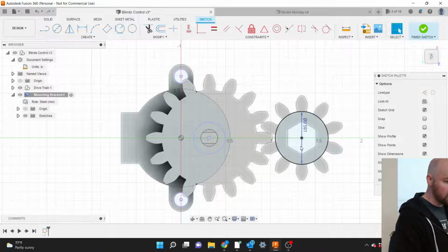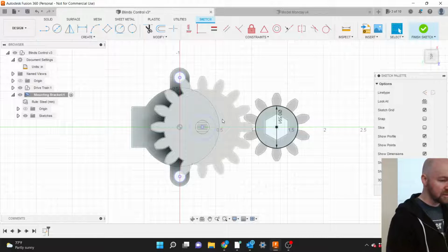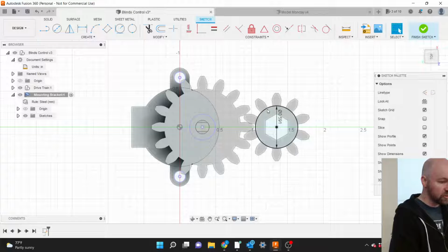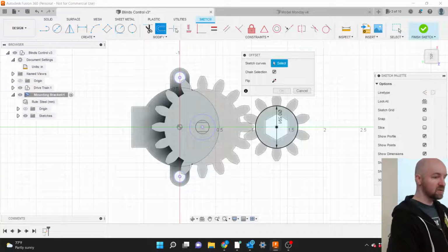And now that we've got all the openings that our sheet metal is going to have, we need to have kind of an outer area, right? So an outer edge. I'm going to create that outer edge by doing a couple of offsets. So I'd like to have a little bit of gap, some sort of distance between the openings of my sheet metal and the outer edge. So I'll create that outer edge by specifying those distances, those offsets that I want.